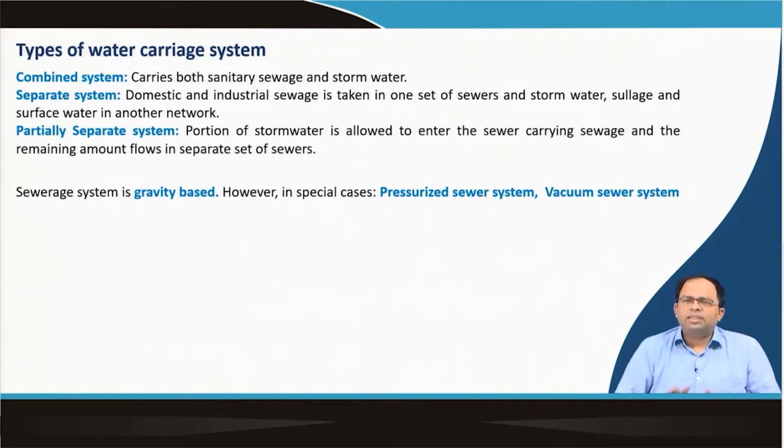One set of pipeline is dedicated for stormwater, another for sewage, but certain things, like the stormwater collected on our roofs, maybe within the layout of the building, within that particular plot, or the sewage from the toilets, is added to the sewer pipeline, whereas the stormwater generated from the streets, surroundings, parks and other places goes through the stormwater drainage network.